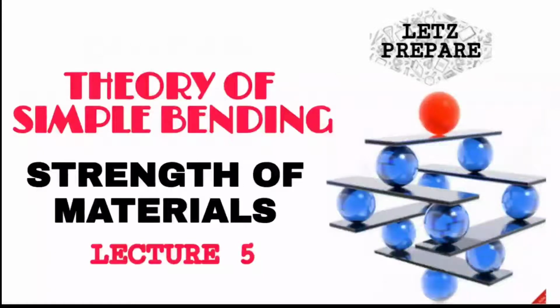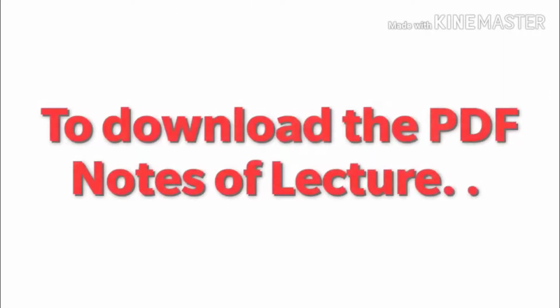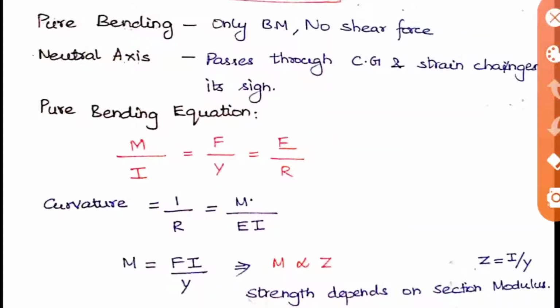Let's prepare on the theory of simple bending. So now we are going to see the theory behind the simple bending process. First, let us see what is pure bending. Pure bending means when a beam is experiencing only the bending moment and there is no shear force created. At that point only, pure bending will be happening.